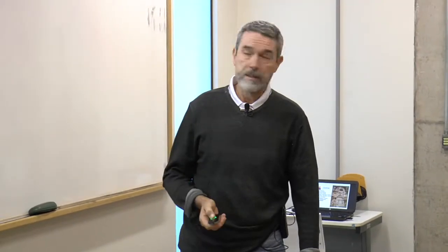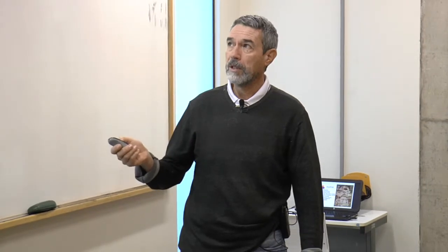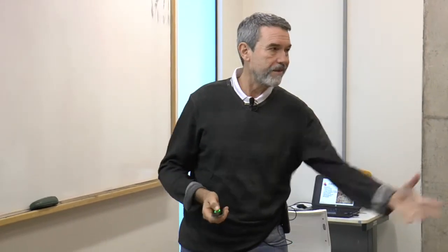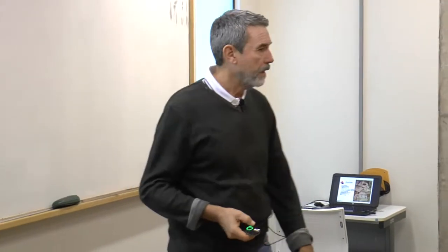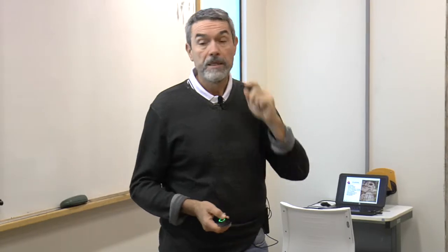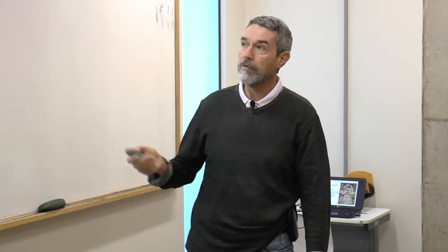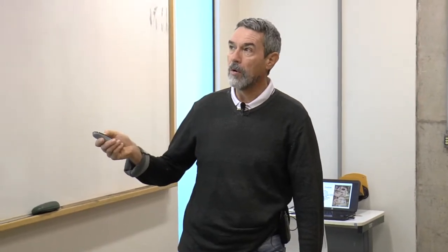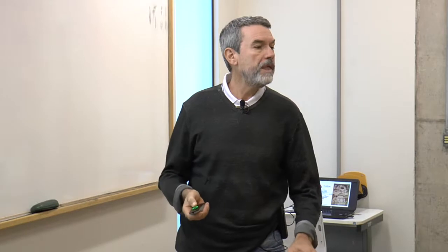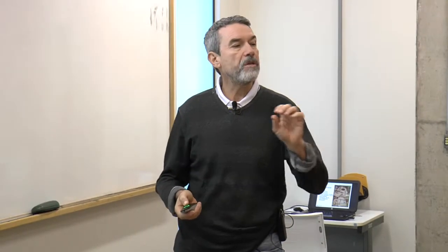Just a brief outline. We're going to give you an introduction on the physics and chemistry of crystal growth. Then there are several growth models, and 3 growth models are widely used to describe the growth kinetics in supercooled liquids: normal or continuous growth, screw dislocation growth, and the 2D surface nucleation growth.